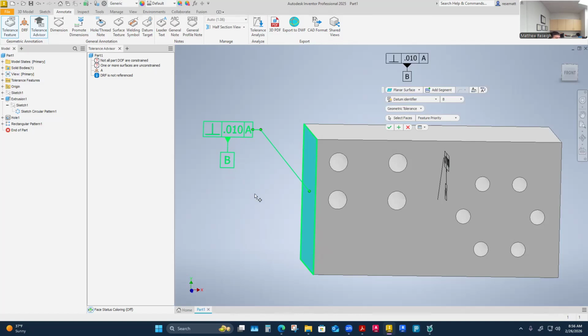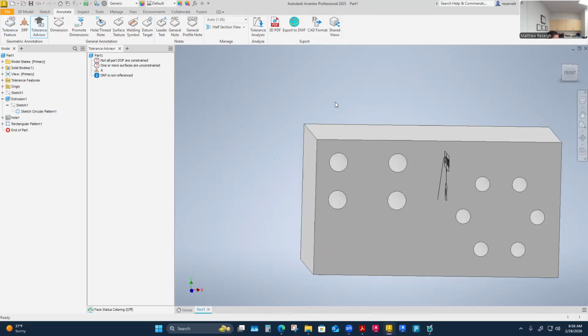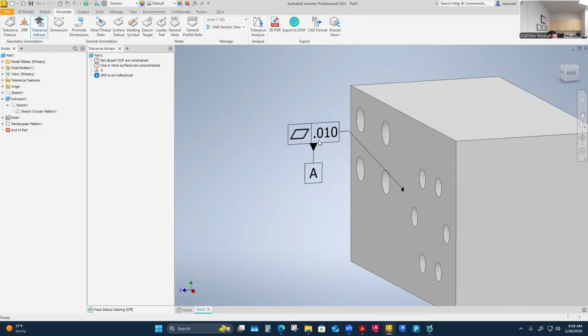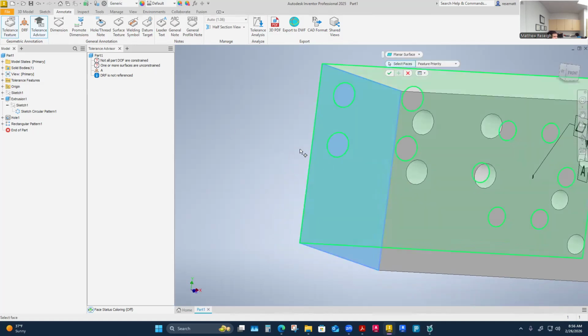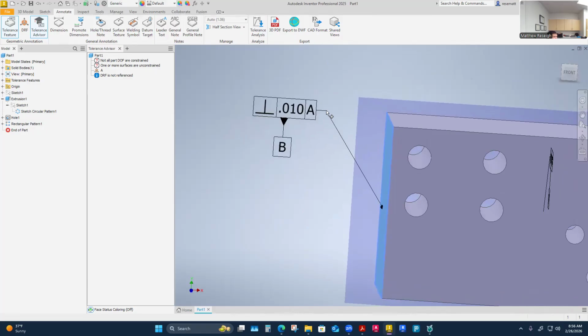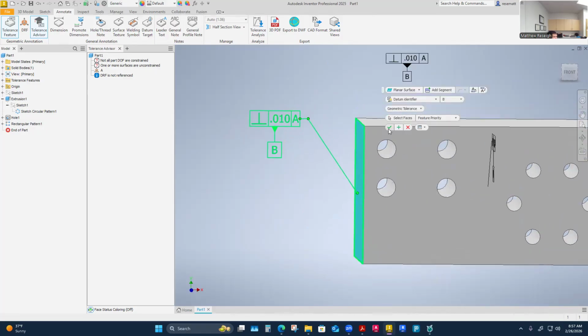This is now going to be considered datum B. So I don't really have to change anything here. Yours did not do that? Yeah. Oh, I don't know. Oh yeah, make sure you have your first one or it will not. That's for sure. Yeah, make sure you do the little check. If you don't push that check, all your hard work goes to naught. It is true. There's like two green checks to get that thing to apply for sure. And then yes, it should be this one as a green check. That's good. Double click.